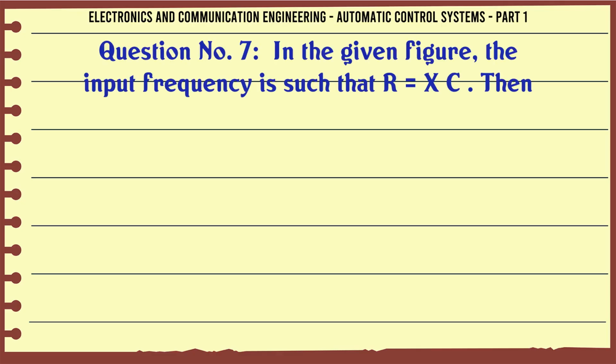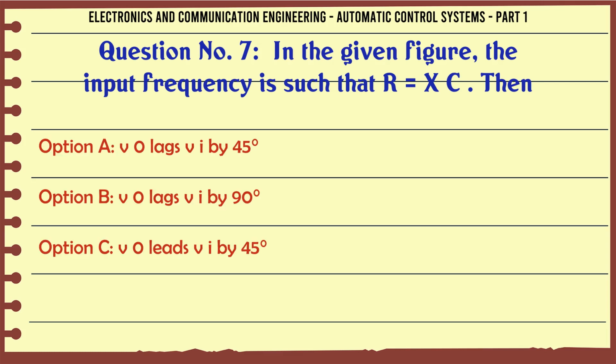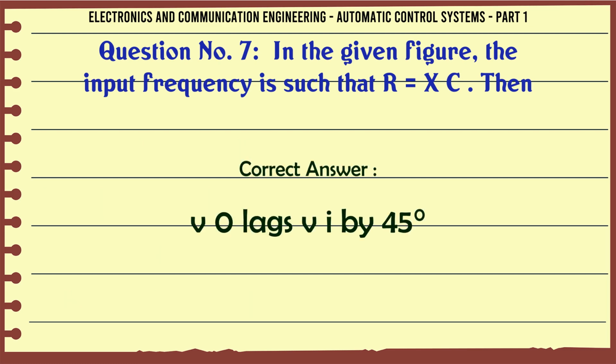In the given figure, the input frequency is such that R = Xc. Then, A. V0 lags Vi by 45°, B. V0 lags Vi by 90°, C. V0 leads Vi by 45°, D. V0 leads Vi by 90°. The correct answer is V0 lags Vi by 45°.